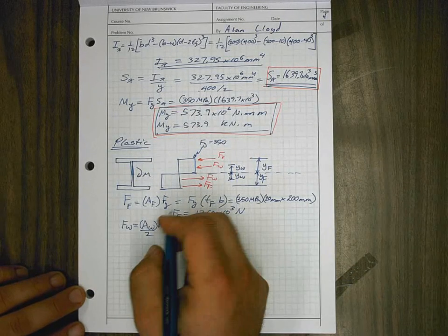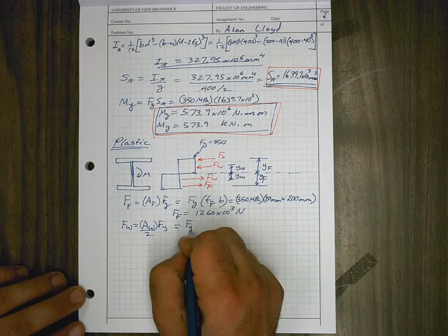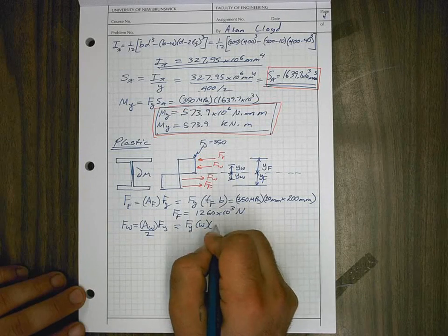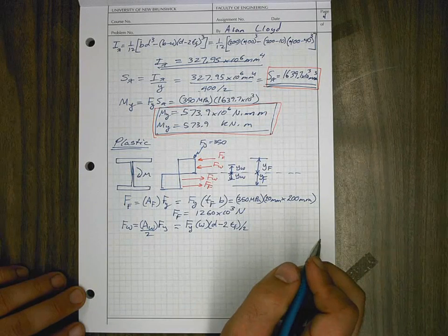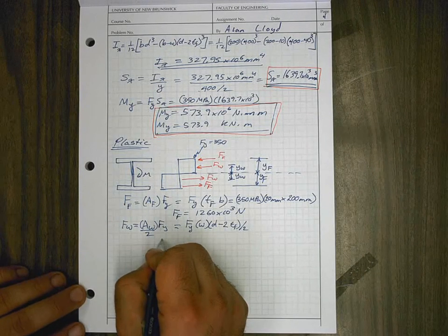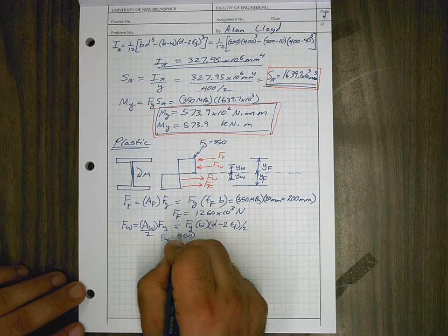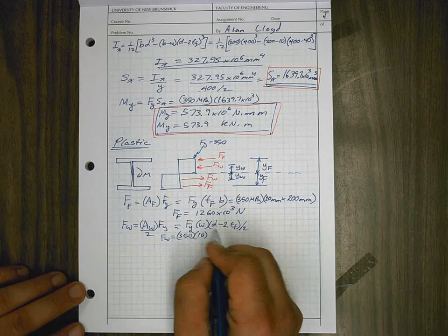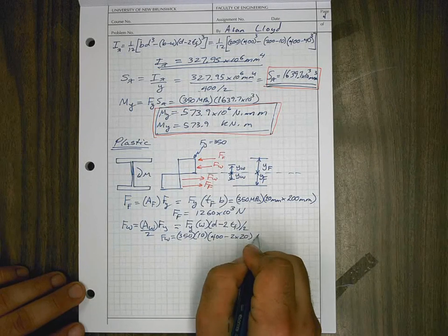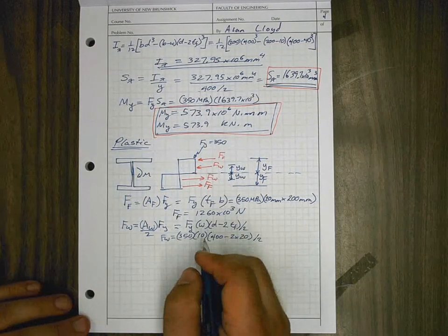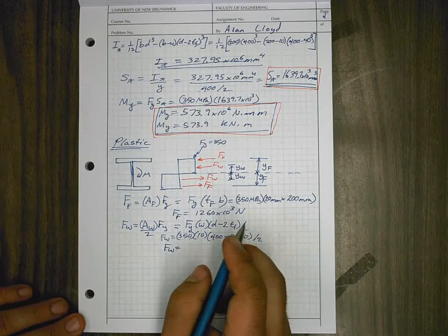And this is equal to Fy times W times (D minus 2Tf) all over 2. And if we plug in some values, we get Fw is equal to 350 MPa multiplied by 10 millimeters is W, multiplied by (400 minus 2 times 20) over 2. Pardon me. And this gives us Fy, or Fw, the web force, is equal to,